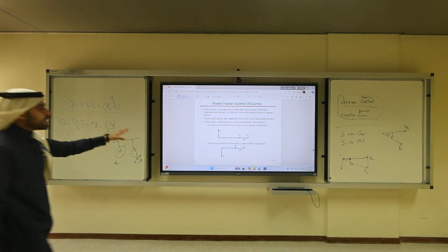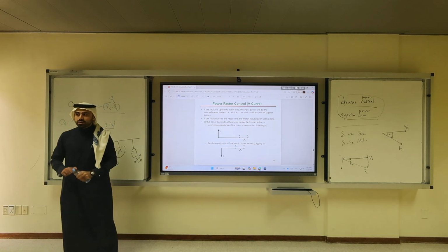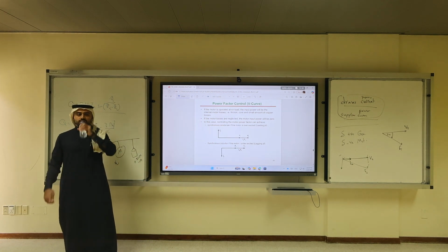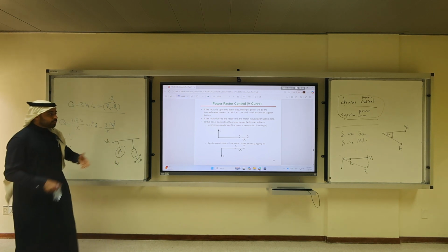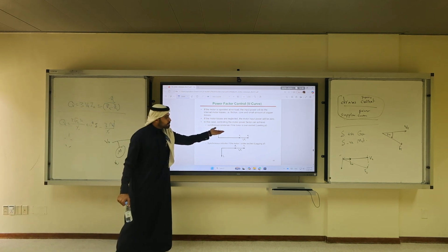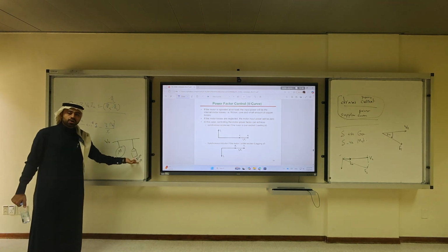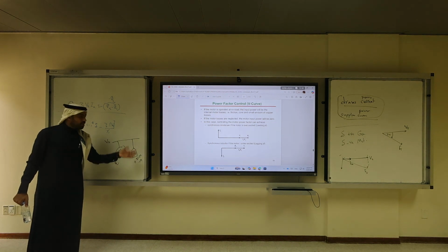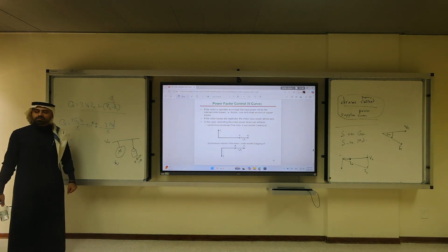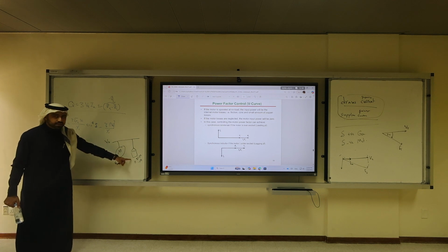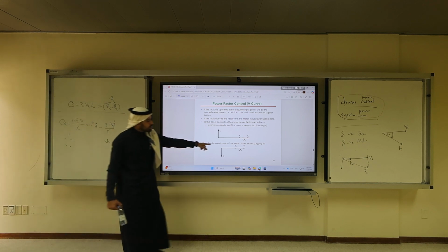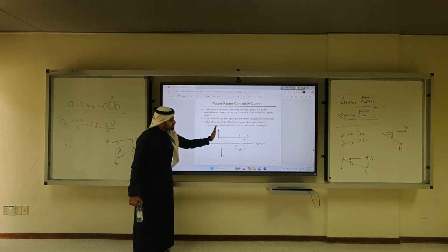So this is one of the applications of synchronous motors, to correct the power factor. Depending on need, if I want them to operate as capacitors, I operate them at leading power factor. I connect a capacitor in parallel with the house or the plant. Then the whole bus would be at unity power factor. If for some reason my house is operating at a leading power factor, I operate them as a synchronous inductor. So here the current is leading my VT by 90 degrees.